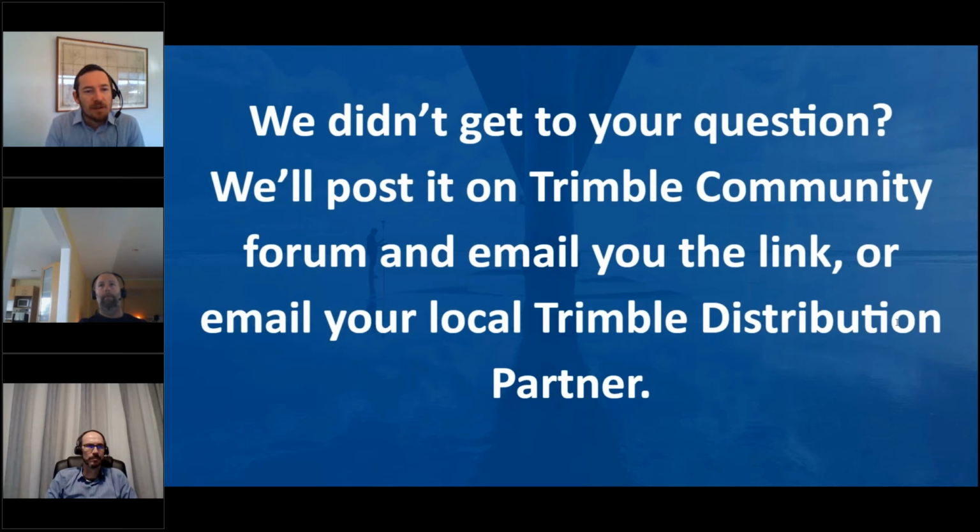Okay, probably the other one that, depending on where you are, you can create a 7-parameter transformation for the older controllers in the coordinate system database that will get you very, very close before doing a site cal. So it might get you down to a centimeter or two, or let's say sub 5 centimeters with a 7-parameter transformation, and they can be set up in the coordinate system database. If you're not familiar with doing that, then have a chat to your dealer and make them stretch their grey matter on how to do those and key them in.